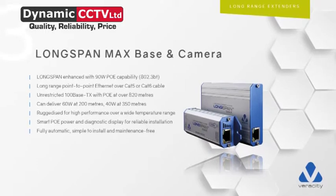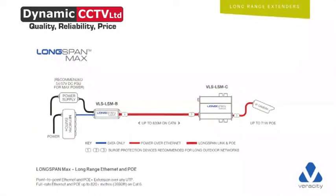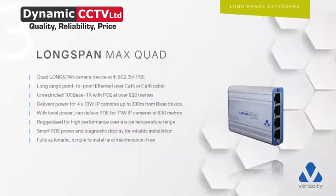A lot of people always say I need 90 watts at that end. So just so we're clear, you get 90 watts at the starting point and you get 71.3 watts at the CPE, which is exactly the 802.3bt criteria. So long span max at the beginning. Not a long span, but a long span max. The reason it's a long span max is you can pump more power into this one from the starting point, which achieves higher wattage, and we can also run the unit at the end as well as the cameras or whatever's plugged into the back of it. That's up to 71 watts, as you can see on the screen. So again, a bit of a game changer. Nathan, for distances and everything else, I would suggest that we talk about that separately.